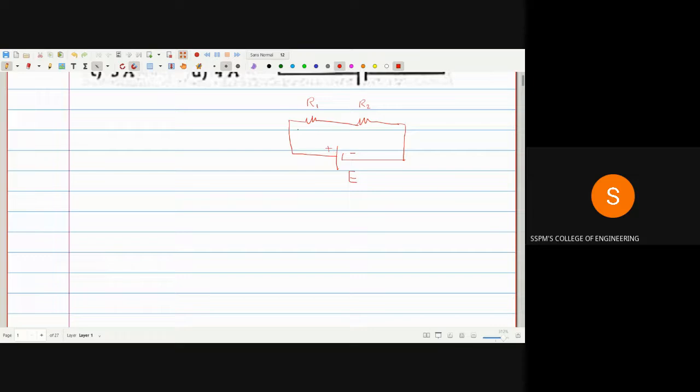You know the current is flowing in the circuit, and the current is always flowing from positive to negative. The current I will flow from left to right hand side, isn't it? And then you can apply KVL here. Apply KVL rule along this path. You may consider clockwise path direction or anti-clockwise. It doesn't matter. Consider any direction for finding the voltage equation. So according to KVL, the sum of the voltage and the product of current and resistance is equal to 0.